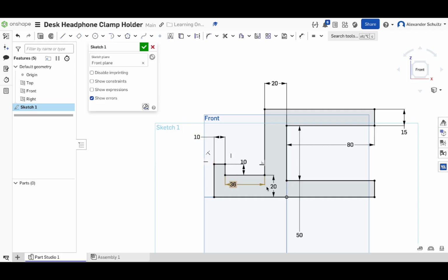Very basic. You can see it's all just 90-degree angles, but I wanted to make this basic shape for people who are just starting, and I wanted to give a simple introduction and help you understand constraints. So to sum everything up, we started at the origin. We started drawing a rough outline of what we wanted using the auto applied constraints, like vertical and horizontal constraints. So this line started out vertical, but we placed a point here, horizontal, we placed a point here.